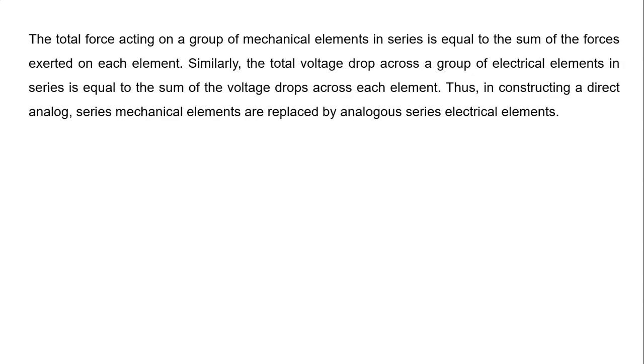Similarly, the total voltage drop across a group of electrical elements in series is equal to the sum of the voltage drops across each element. This also we have seen in case of series electric circuit. Thus, in constructing a direct analog, series mechanical elements are replaced by analogous series electrical elements.